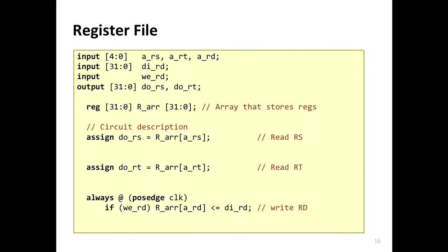But the memory we are going to implement has synchronous write, because the write enable will be checked at the rising edge of the clock, and the data input will then be appropriately stored into the register file. So when you do an add operation, your result is going to be stored in the address of the destination register. Simple. So we have a register file now implemented.